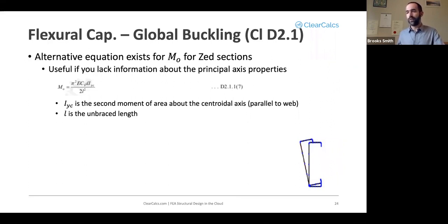So a couple of questions here. LEY and LEZ are the unbraced lengths of the beam. Usually they're just a pure unbraced length. If you have a bit of bracing that provides rotational restraint as well, that is essentially a fixed connection versus a pinned connection, then it's going to be unbraced length times a K value.